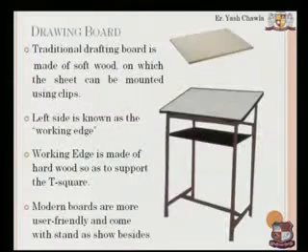Well, if we have a sheet, we need to put it somewhere. It cannot be a scribbled place. We don't want to make the sheet dirty, because if it is dirty, then it might be interpreted as something else. If I have a dot on the sheet, it might be interpreted as a hole, and that engineer might drill a hole where it is not required. So I don't want that. I want the sheet to be neat and clean, and if I'm drawing a single line and the surface beneath is rough, then my line will be a zigzag instead of a straight line. So I need a plain surface.